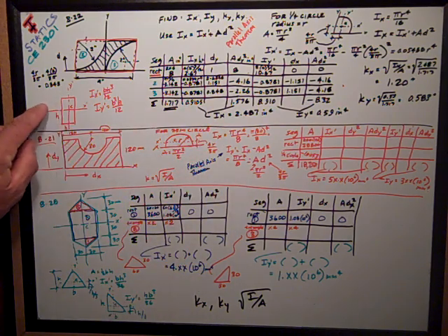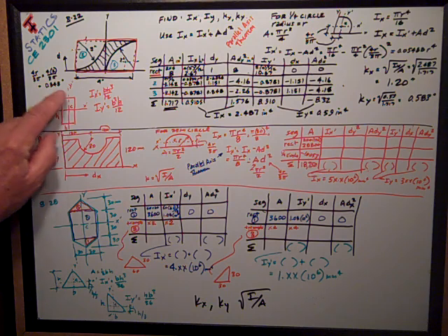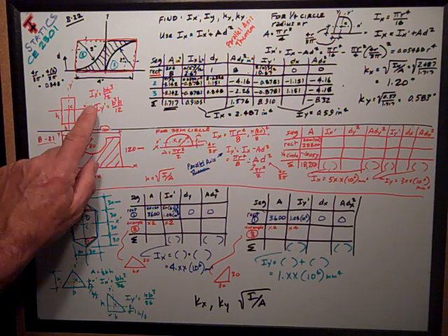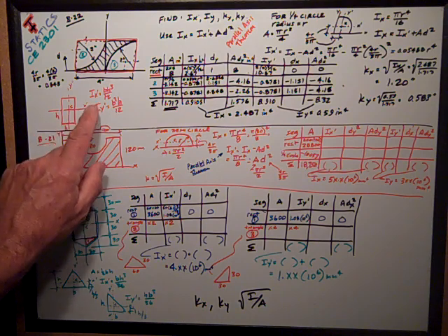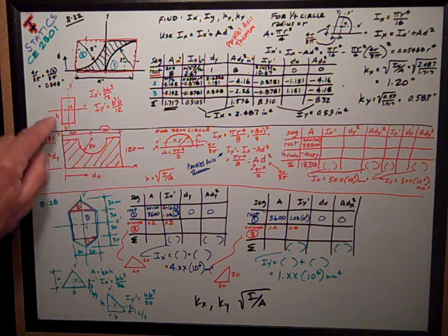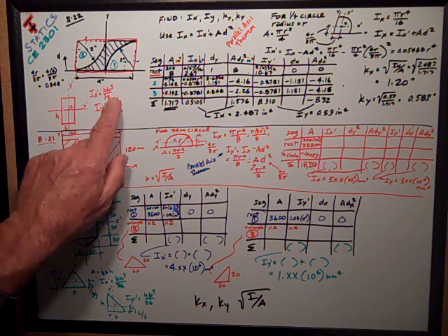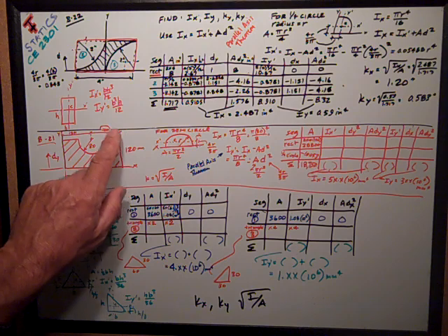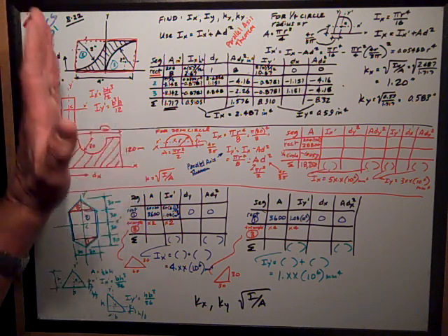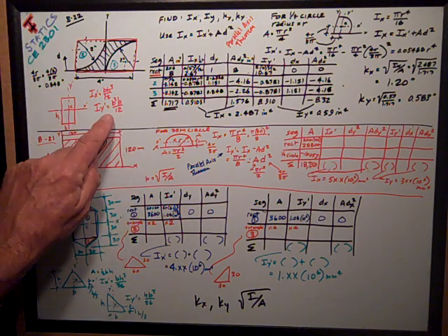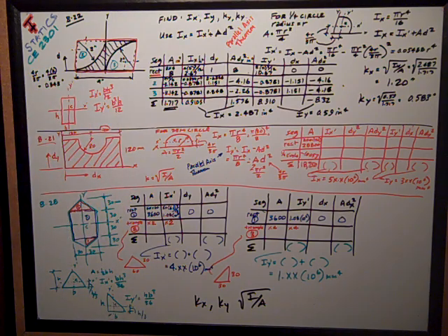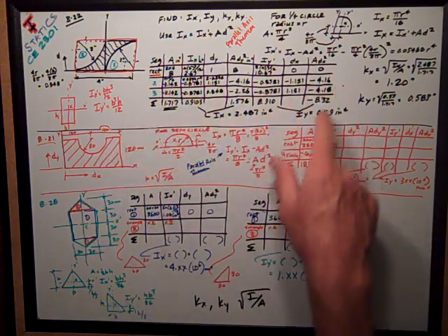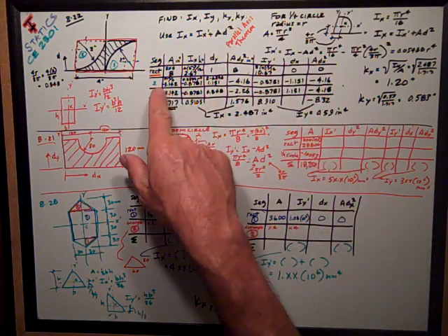Also for the rectangle shape, I'm going to use these properties. The moment of inertia about the centroid axis, Ix prime, of a rectangle of dimensions b wide and h high, is bh cubed over 12. We're going to use that number a lot. And if I rotate my axis 90 degrees to the y prime axis, it's just b cubed h over 12. Same thing. So I make a table, because I like tables because it helps me remember to do everything.